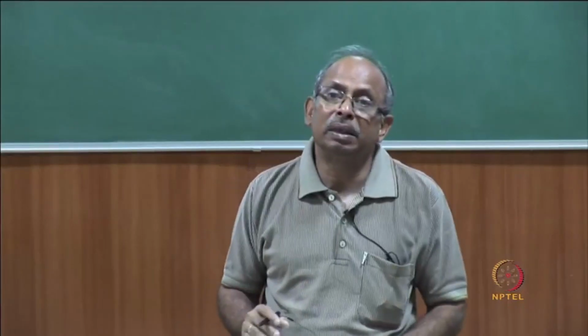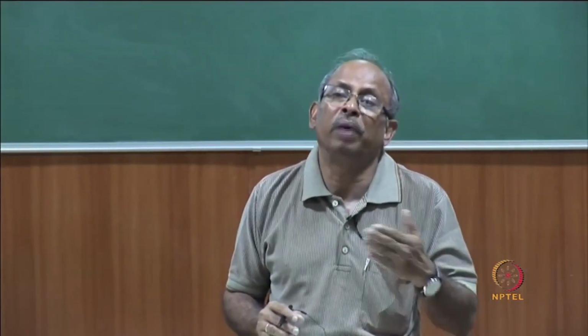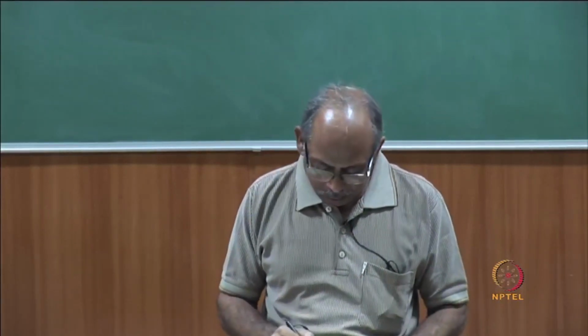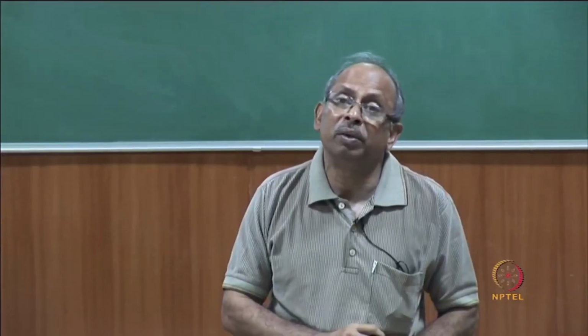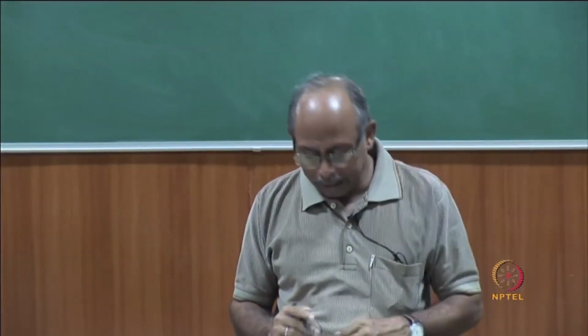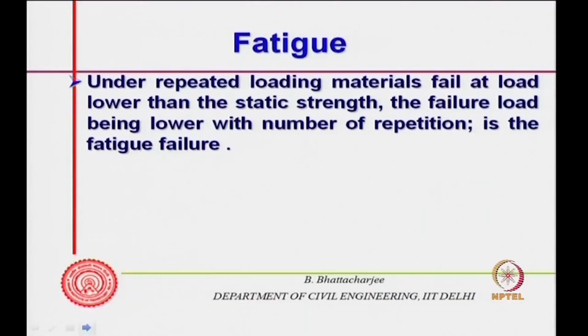So, this reversal of stresses is related to what is called fatigue strength. In fact, the load any structure or structural element can carry under reversal of stress is much lower than the load it can carry in static conditions. So, fatigue is related to repeated loading. Under repeated loading, materials fail at a load lower than the static strength, the failure load being lower with the number of repetitions, and this is a fatigue failure.